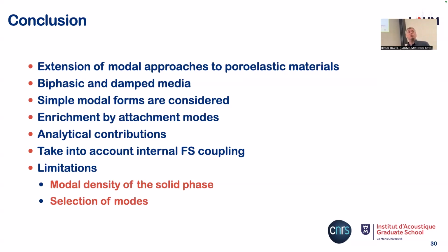And of course, these methods are limited, but this is the classical limitation of porous materials, and especially because we have a modal density of the solid phase that, yes, the solid phase comes into this mid-frequency regime very early. Okay, so this is some results, which was also to show you that for different physics, okay, we can adapt classical techniques. But for that, what we need, this is to have a good insight on the physics that you model, and also a good insight on the reduced order